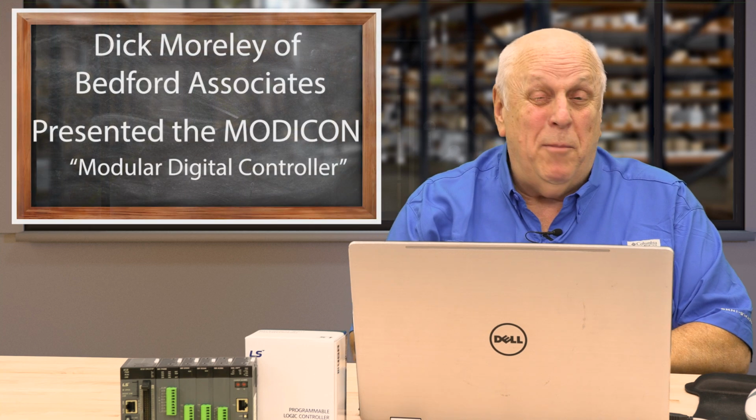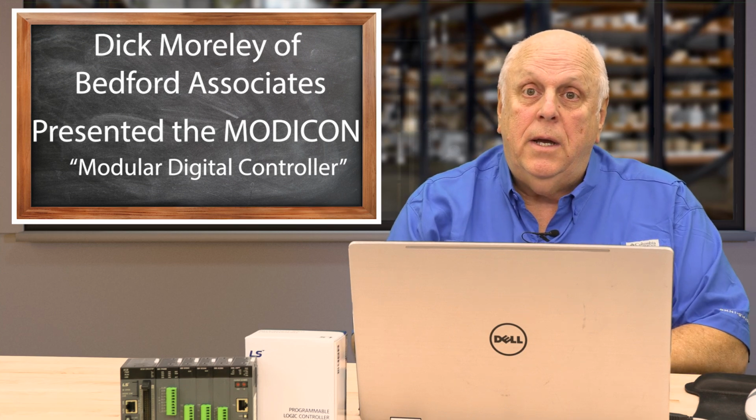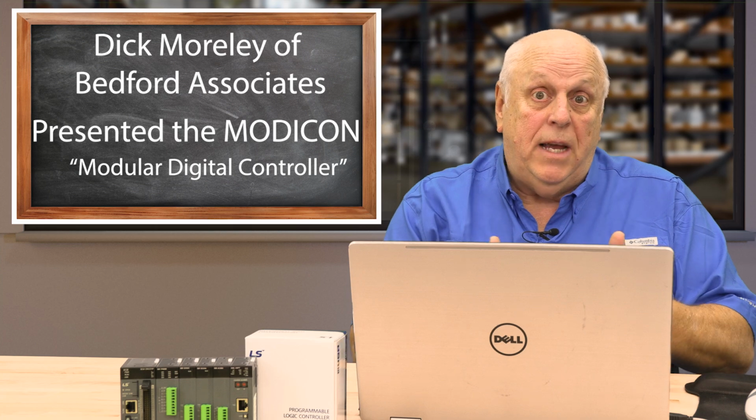Before I get too far into IEC 1131, there's two other things I'd like to cover here. You have to understand that the PLC has morphed and evolved over about a 50-some-year period. It came out around 69. And remember I told you we programmed with handheld programmers, and then DOS and then the Windows. And as they were evolving, they got more powerful processors. And electricians like me were making more demands. For example, on a sequential process, ladder is not conducive to a sequential process. It's hard. So, in the old days, we had things called drum sequencers.